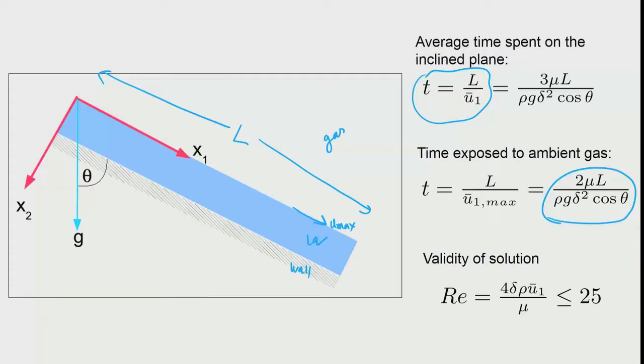So, that is from the Reynolds number. We see that the Reynolds number as defined here can be used to check that it is less than a critical number. This is the critical Reynolds number, and in this problem it turns out to be 25. So, smaller is always better. If you ensure that the numbers you got are within this limit of 25, then the solution you got is reasonable, and you can use those numbers as meaningful solutions out of the problem that we have.